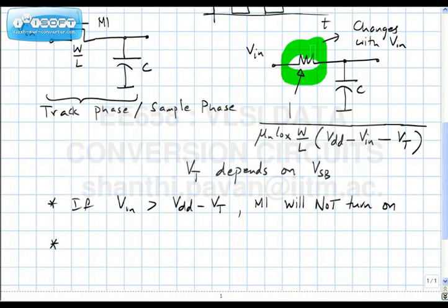So this is clearly, in very loose, inaccurate terms, you see that the pole of the system is moving along with the input. The whole notion of poles and zeros only works when things are linear. But so clearly when the so-called poles start moving with the input, things are absolutely non-linear.